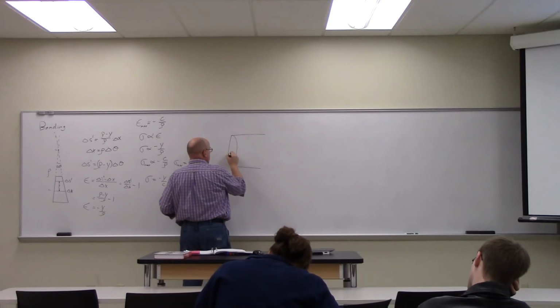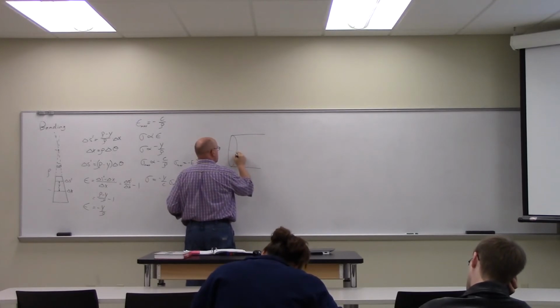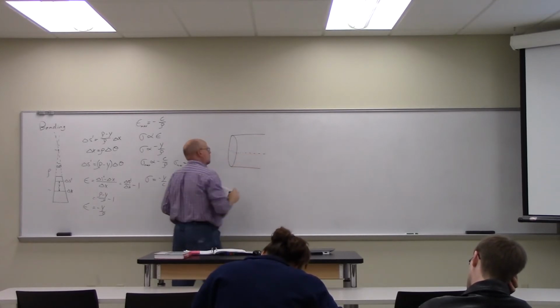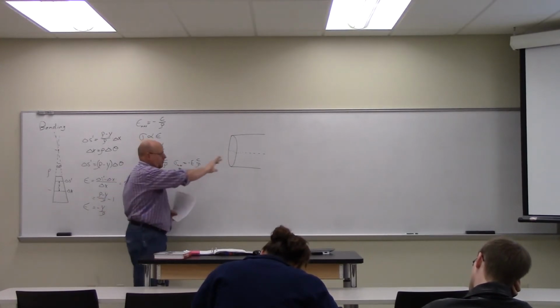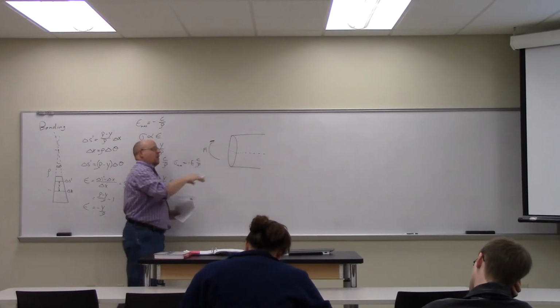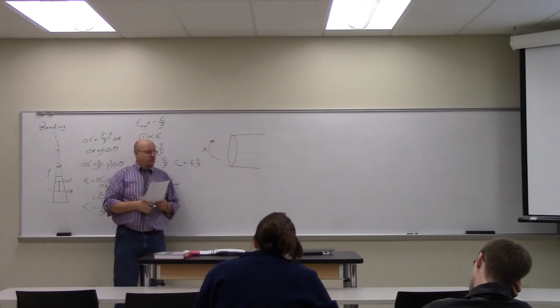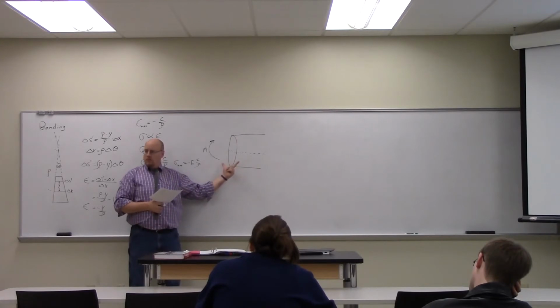We have this neutral axis here. And that's the neutral axis. When the bar is bent, the moment applied is this one. When the bar is bent with this positive moment, the neutral axis is not deformed. Everything above it is squished, everything below it is stretched.